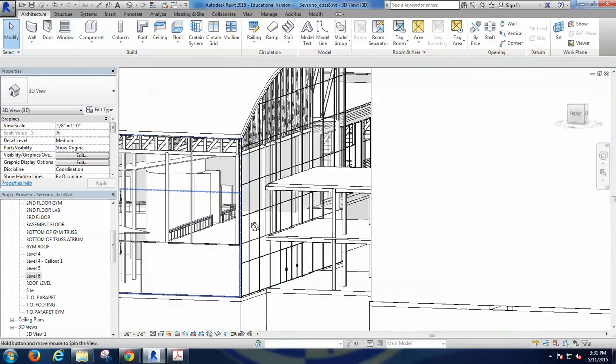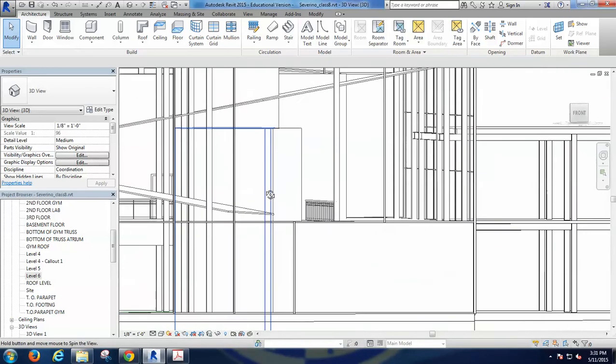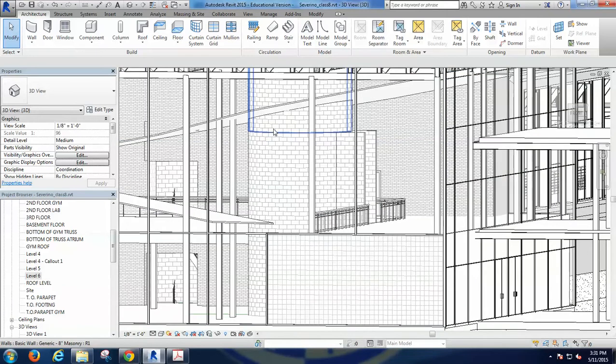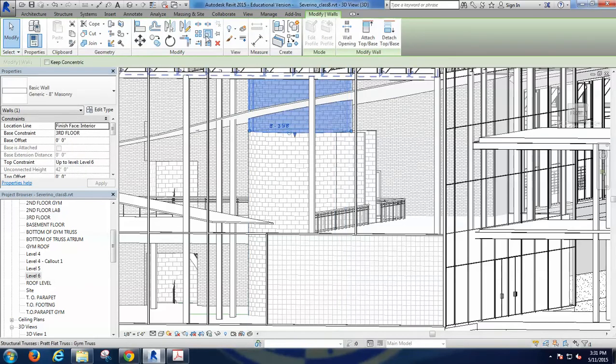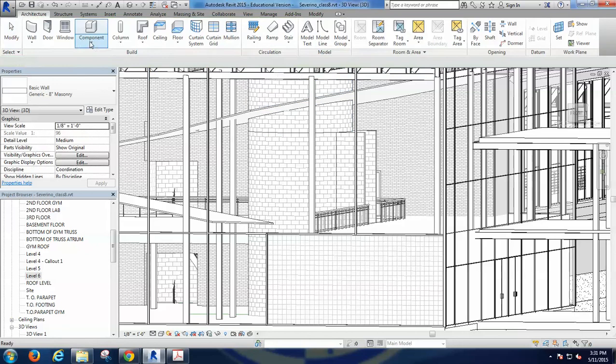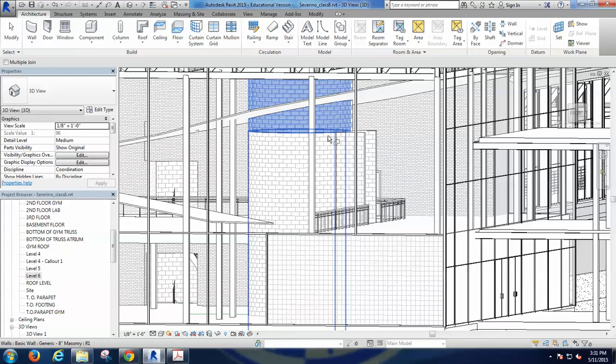Okay, something I haven't shown much is, you see how these two walls here, we have the wall of the stair that is cylindrical and the semi-cylindrical space underneath. You can actually select the walls and join. If you use this tool, join geometry, this allows you to connect different parts by selecting them one by one, and you see how they get connected.